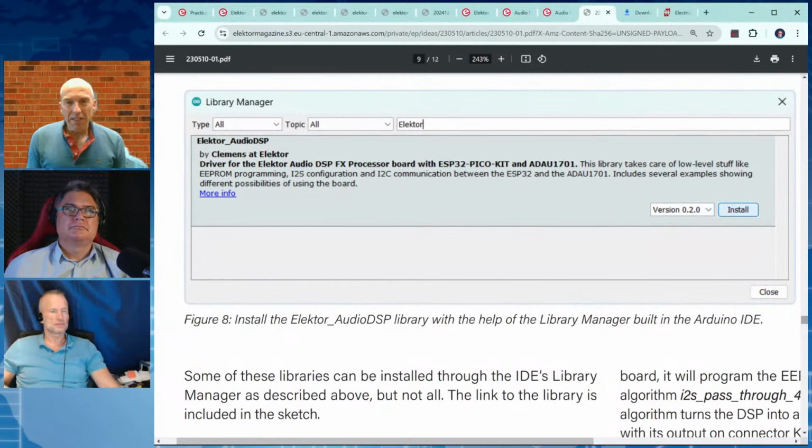Some of them I did, indeed, because they are examples. There is a Sigma Studio algorithm that's really simple, that just pumps I2C audio from the input to the ESP and from the ESP to the output. And I make that on 2 sample rates, so you can have it on 44.1 and 48 kilohertz. And so those are very simple algorithms, and they are in there.